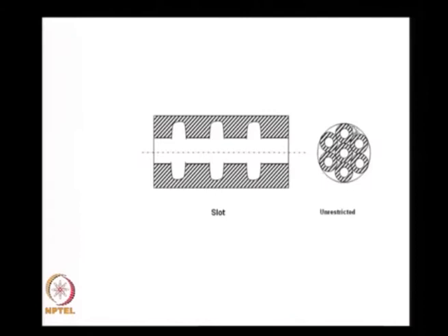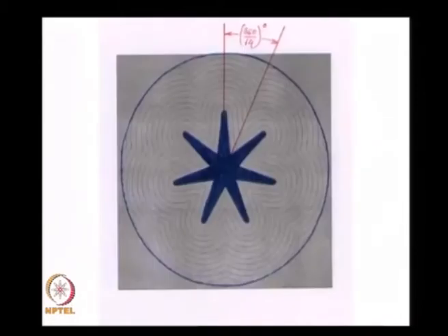Such things I have not seen being much used in practice, but when we see maybe rocket assisted takeoff for planes and all that, we will try to see whether some of these things can be used. Therefore, to summarize, we talk in terms of neutral burning, progressive burning, regressive burning, and everything decides on how the surface area keeps changing. Having said that, let us come to this particular problem of a star grain. Here I show the end view. Let us keep our discussions clear.